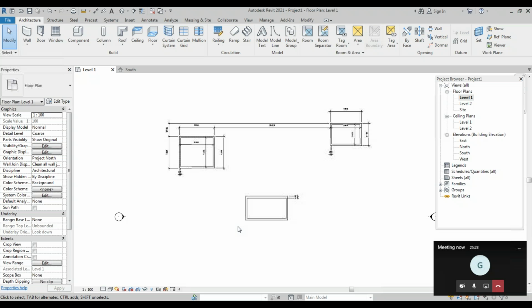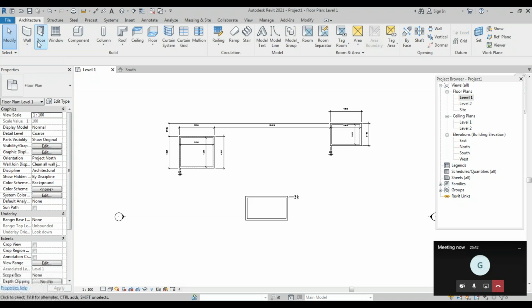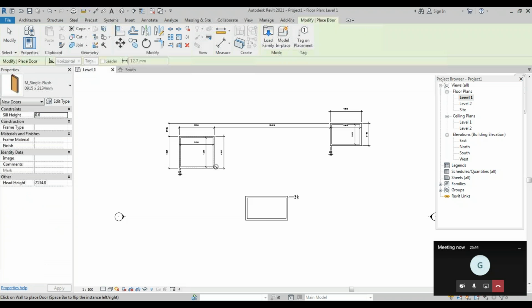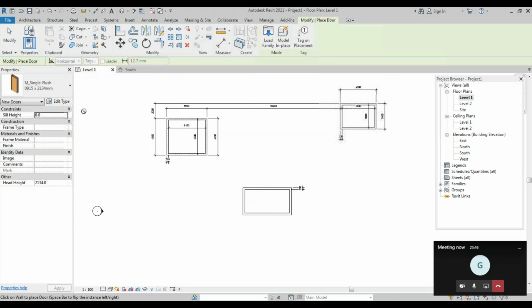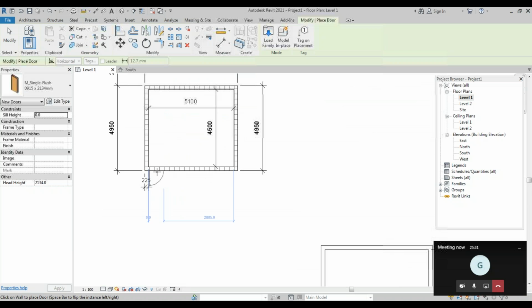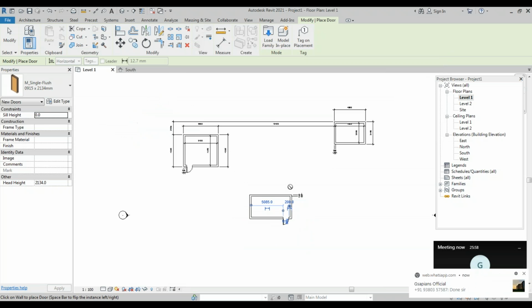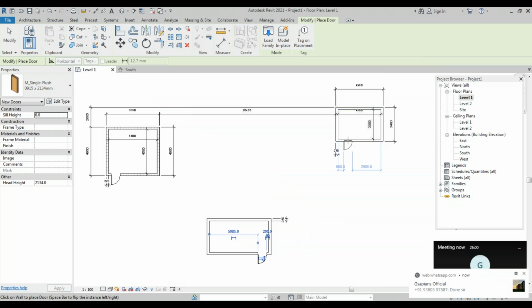What I'm going to do is how to add a door. So if you go near this, you will find the shortcut. DR is for door. WN is for window. So what I'm going to type is DR. I'm typing DR. Automatically the door came. See, click here. DR is the door. So the moment you click the door, you can add the door in this direction probably, so that I can make you understand how important this software is. Okay. So I click here and I click here.